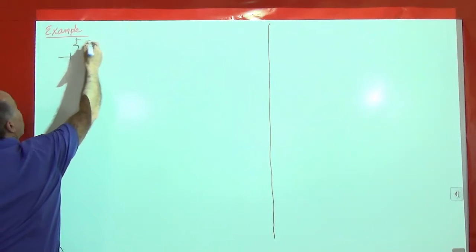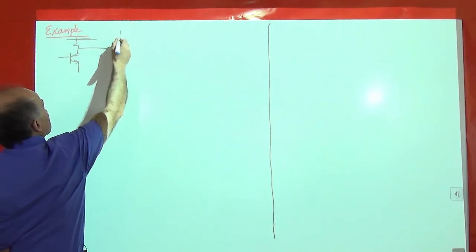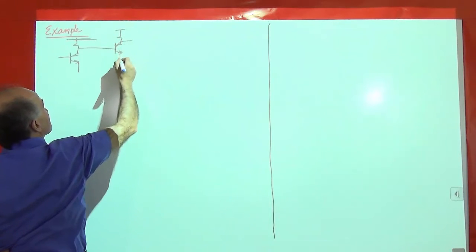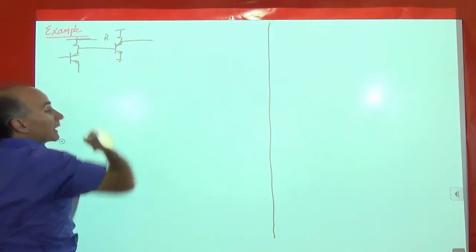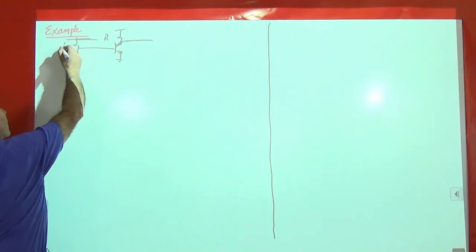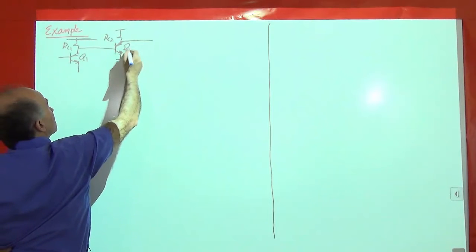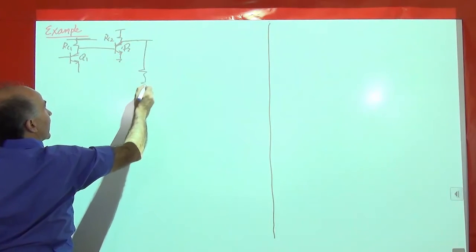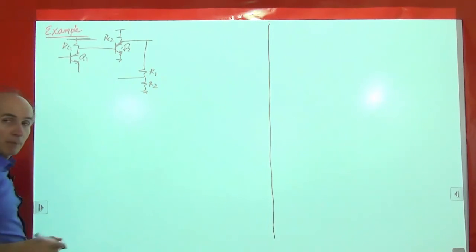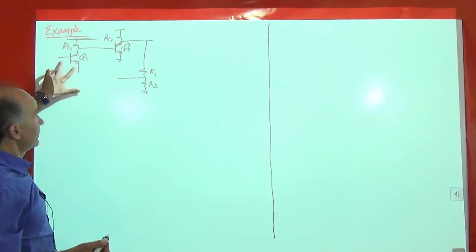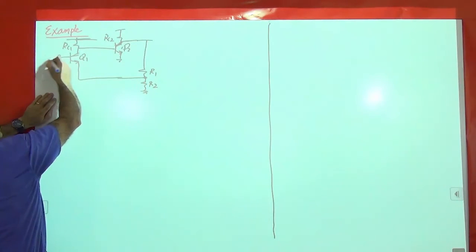We saw this before: I have a two-stage amplifier and I would like to apply voltage feedback. So RC1, RC2, Q1, Q2, and I took this, divided it down, R1, R2. I generated a voltage, that's my feedback voltage. Then I said, well, this device can act as a subtractor, so why don't we just connect this here? And that's our main input.